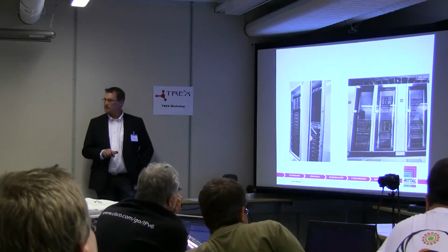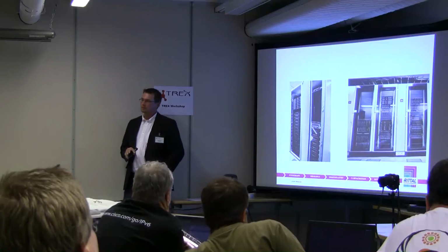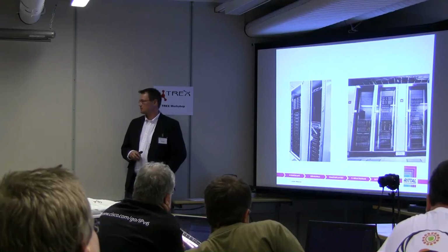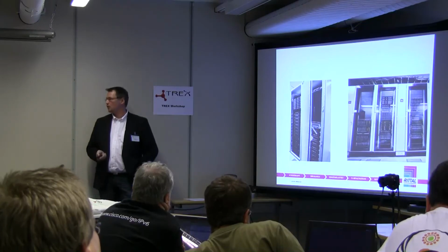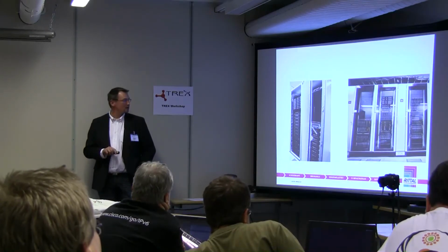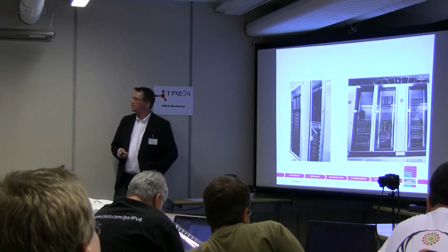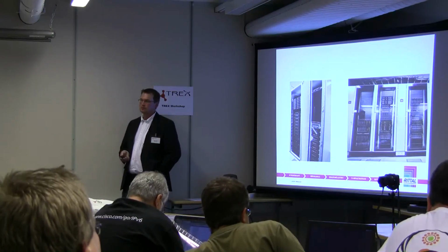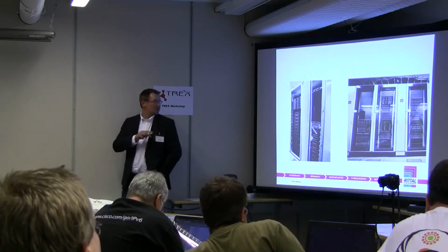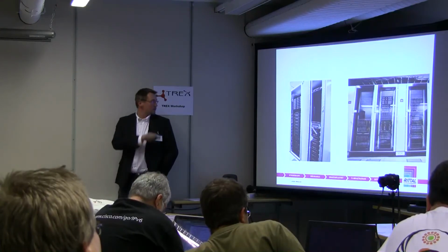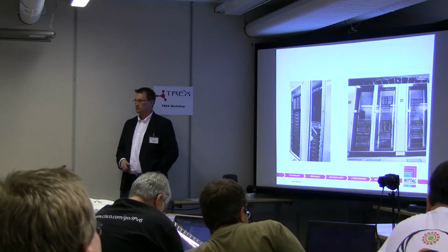This here is a closed system, but the same effect applies also in a cold air system: we should cover all these empty units. Then all the air that goes into the cold air, into this closed rack, can go only through the servers and nowhere else. It sounds quite simple, but unfortunately when we do site surveys before new installations, we still find racks like this and even worse. An open environment with a rack with 2 or 3 servers installed and nothing else.